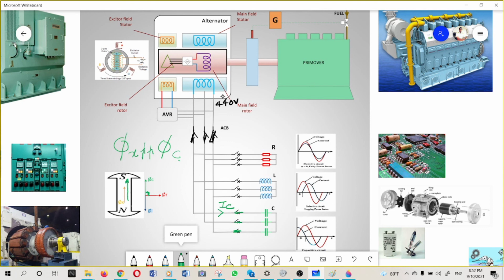In return it will tend to increase the voltage. But it will not cause any retarding torque through magnetic interaction with the rotor field. It will not impact the rotation of the prime mover or give any retarding force on the rotor. But as the magnetic field strength increases, it will tend to increase the EMF.